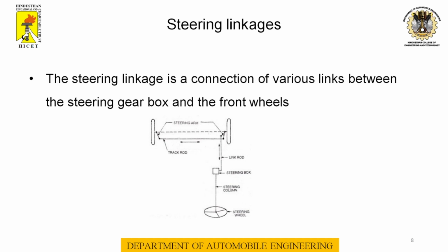When the steering wheel is turned to the right or left, the pitman arm swings from one side to the other. The movement of the pitman arm gives an angular motion to the front wheel through the steering linkage. The pitman arm, otherwise known as the drop arm, is connected directly by the connecting link, and the motions are carried out according to this arm.